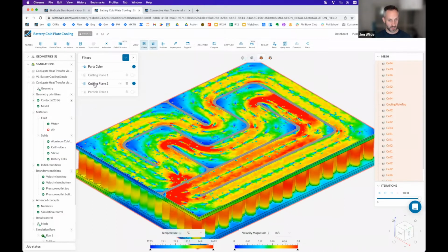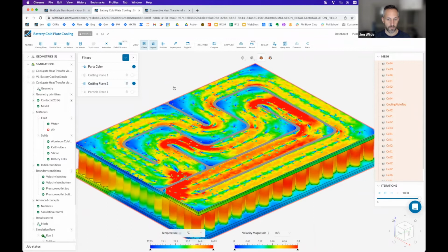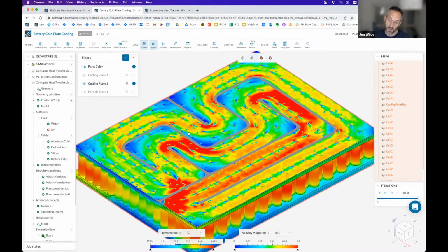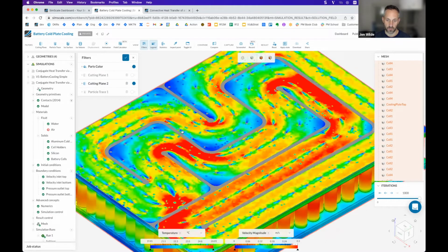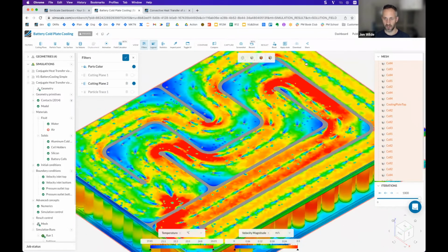So on the side here, I've got a few things set up. You can also just add them, but I've got a cut plane kind of higher up, just cutting through one of the... Oh, you're cutting through, okay. Mm-hmm. Yeah, I think I'm going to select it right, so you can see there's a weird like pink outline around the outside. And the idea, I guess, or the thing that seems kind of weird is that these essentially meant to be turbulators aren't really doing much. They're slowing the flow here and there. On the right hand side over here, they're actually just directing the flow to the side, so it's not passing through the middle. But it's not really making the flow super turbulent.